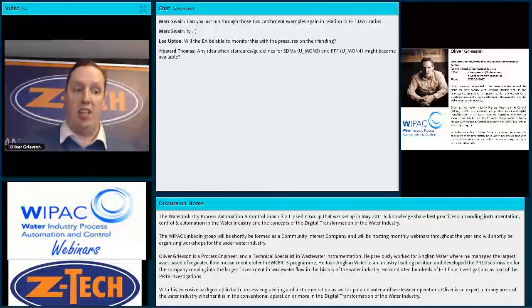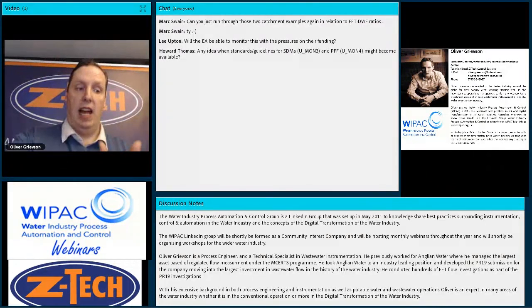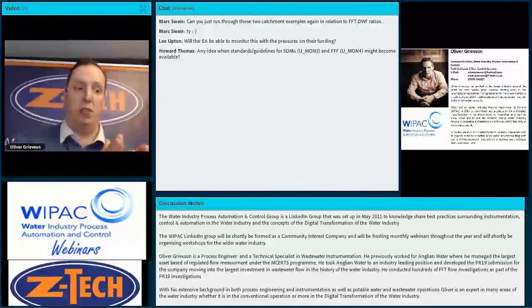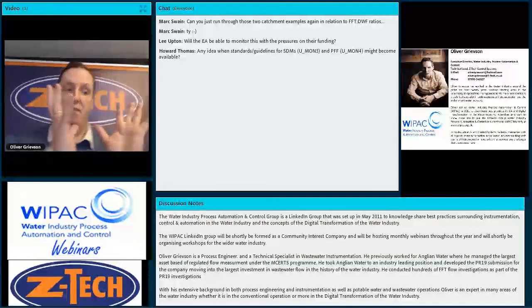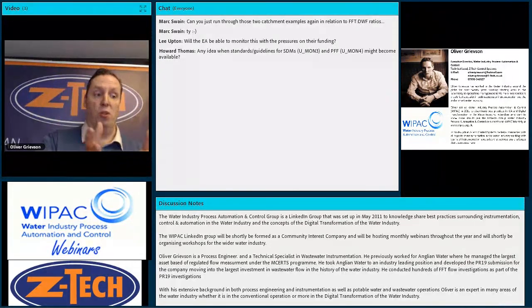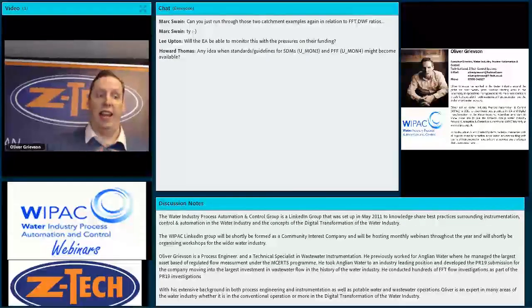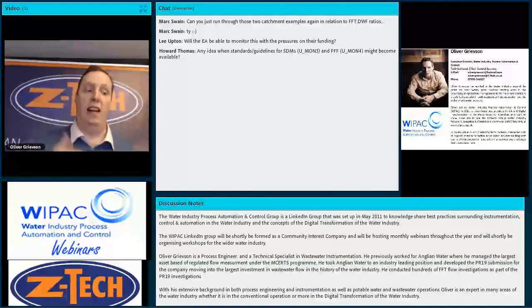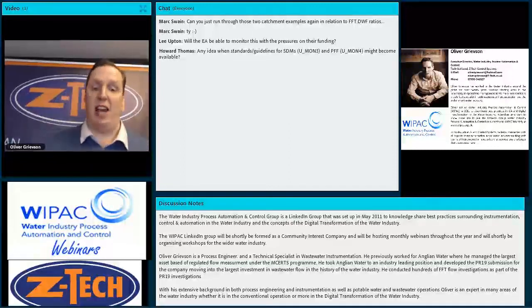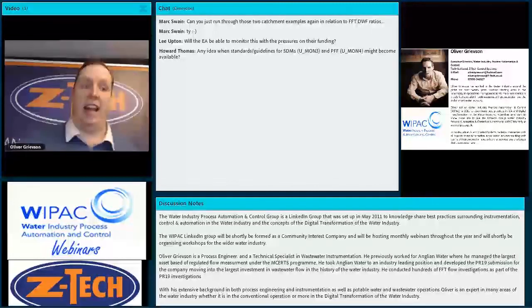It's going to hit the sewer very quickly, and it's all going to hit the sewer in a relatively short time. So imagine a very steep valley, which is all concrete lined. It's all going to get to the bottom of that valley at the same time. It's all going to run into the sewer at the same time. It's all going to hit the wastewater treatment works at the same time. That way you're getting a very short burst of flow hitting the works.